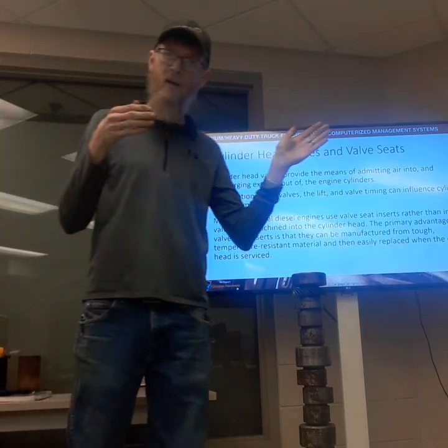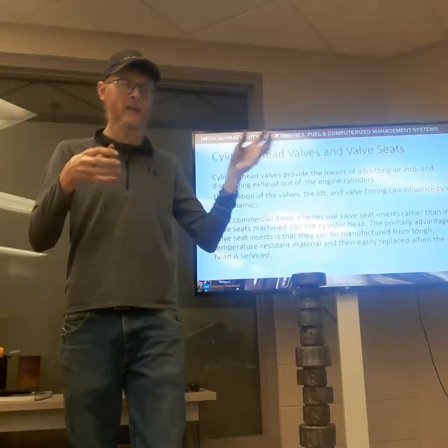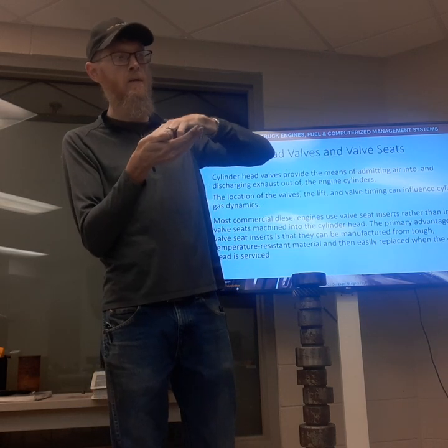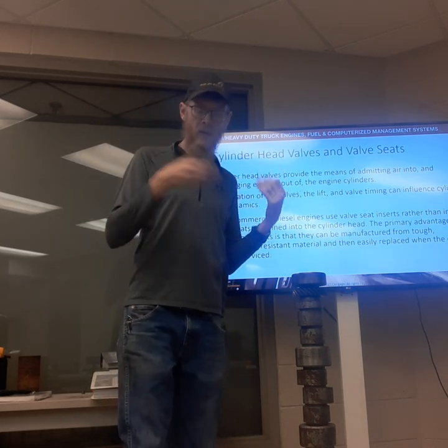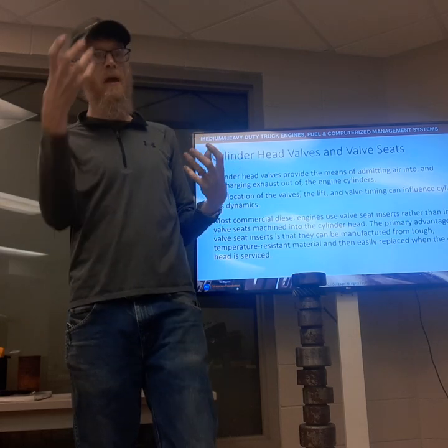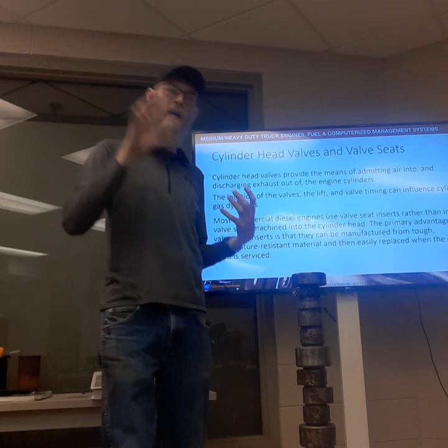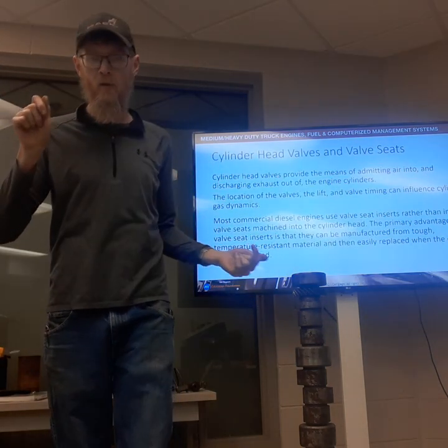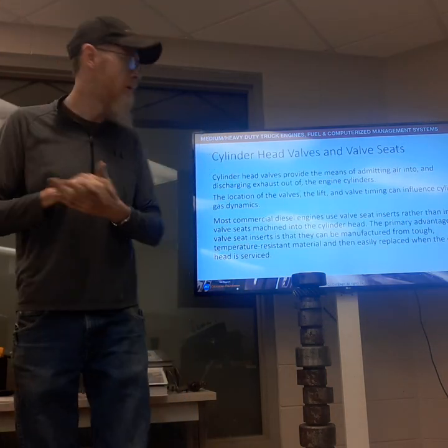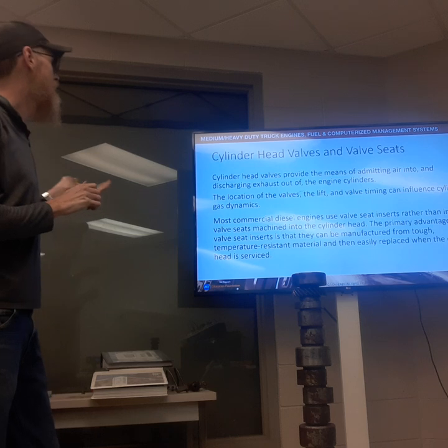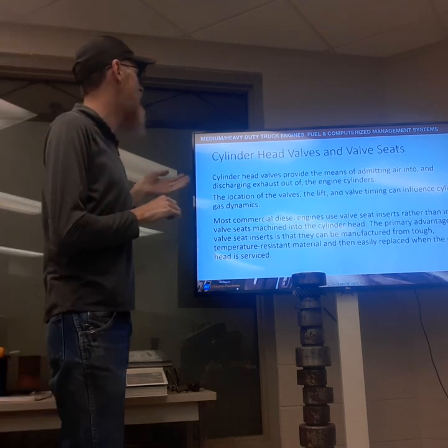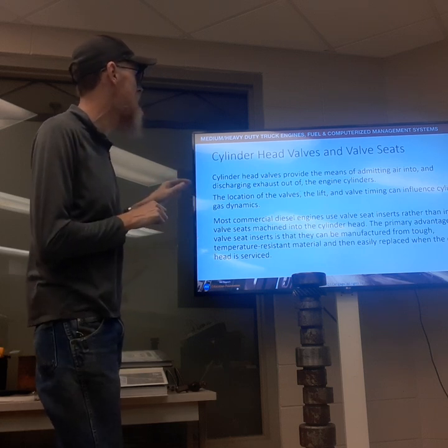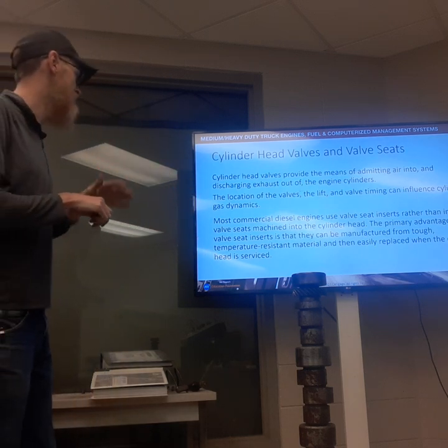If it's the intake valves, it is a means to open a port to let fresh air into the cylinder. And if it's our exhaust valves, obviously when we open our exhaust valves, it connects us to a port through the cylinder head that gets our burnt fuel and air out to the ambient air. Cylinder head valves provide the means of admitting air into and discharging exhaust out of the engine cylinders.